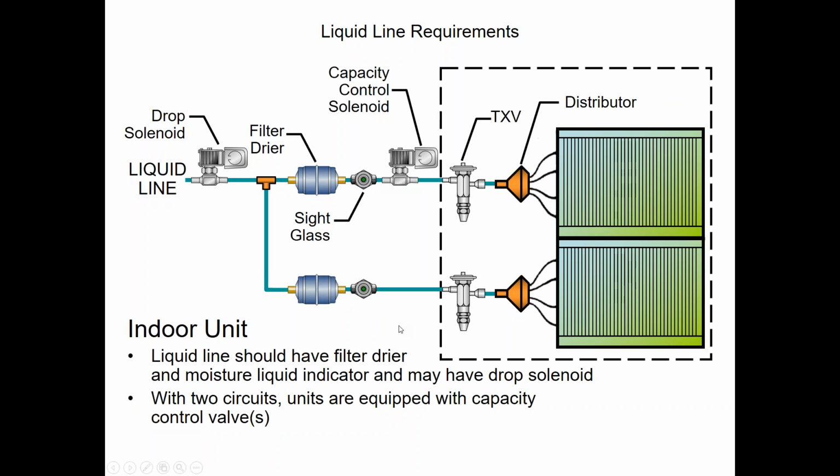Just like residential, a residential condensing unit comes with a weighed-in charge from the factory that is enough refrigerant to work on a system with 15 feet of interconnected liquid line. Commercially, these numbers are found in the product data book that I showed you. The product data book will say this particular tonnage unit requires this much refrigerant for 25 feet of liquid piping.